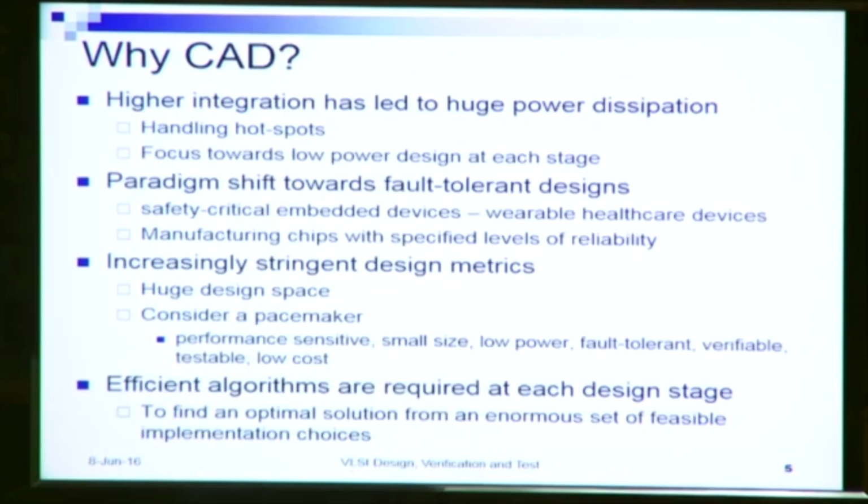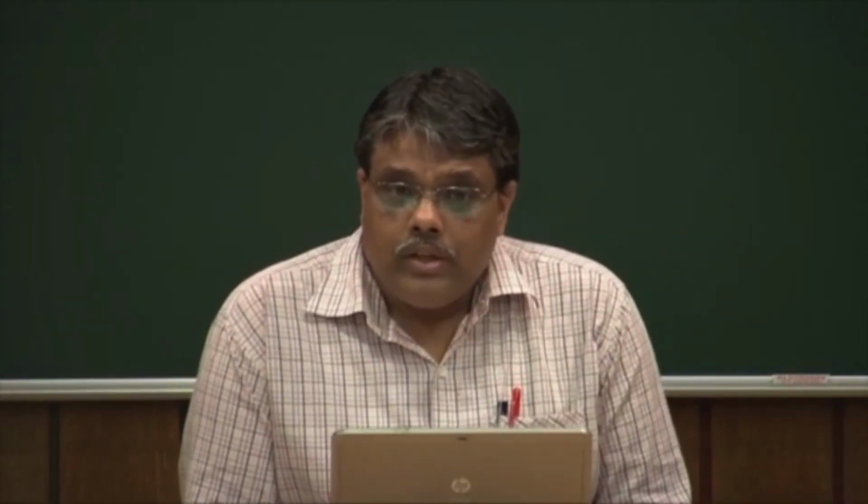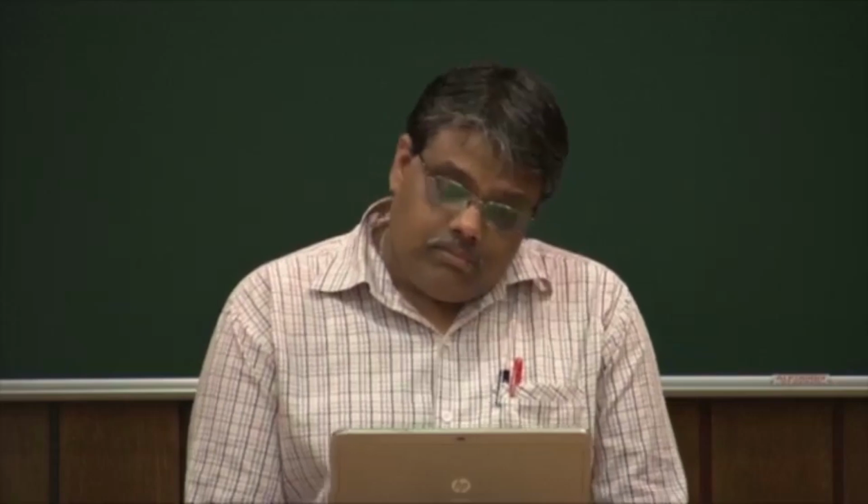Also, higher integration, as we said, many transistors within a chip, will lead to huge power dissipation, because all these transistors within the chip, each of them will leak power, and hence there will be huge leakage power, and correspondingly we will have hot spots generated within the chip.